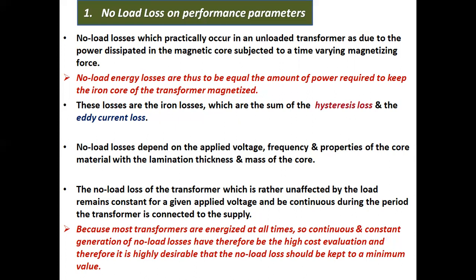So, continuous and constant generation of no load losses therefore carries a high cost evaluation, and therefore it is highly desirable that the no load loss should be kept to a minimum value.